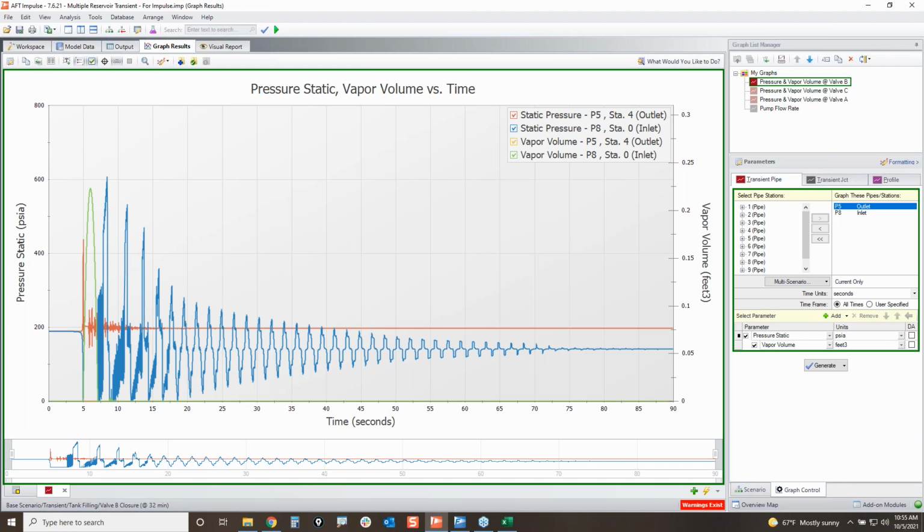Now, if you are asking for Fathom XTS, can you do a smaller time step? Instead of doing 30 seconds, could you do a 5-second time step in Fathom XTS? Or maybe even a 2-second time step? Yes, you still can. You can do whatever you want with the time step. It's going to make your XTS model run a lot longer, and it's just going to give you more resolution. But keep in mind, no matter how small you make that time step in Fathom XTS, you're not going to be able to see what is shown right here.